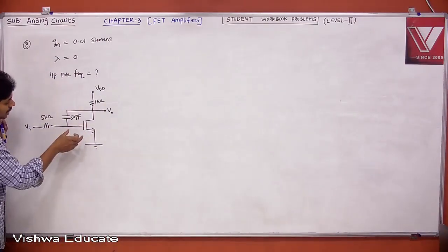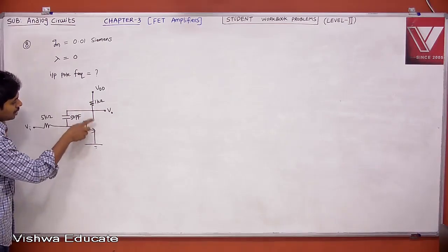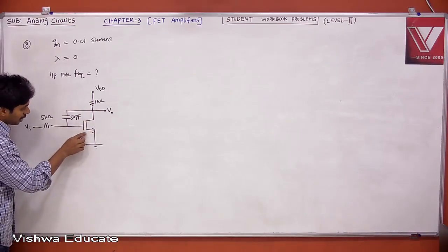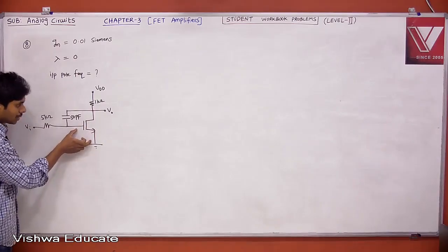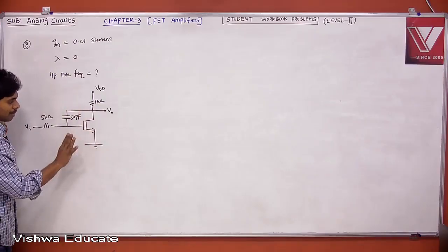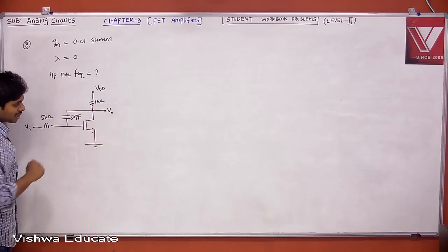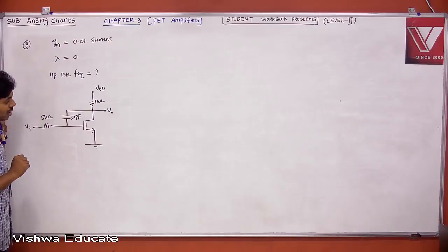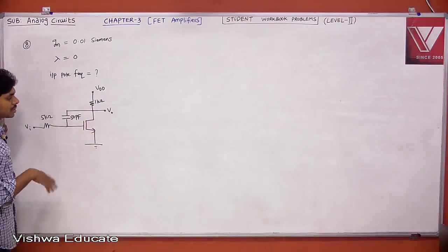It says to neglect MOSFET internal capacitances. Actually, there is gate to source capacitance. Strictly speaking, the bulk is connected to ground, so gate to bulk capacitance is there. It says you can ignore those capacitances, the drain to source capacitance, which is because of the reverse biased PN junction at the drain, and the Miller capacitance which is due to overlap. All those things can be ignored.